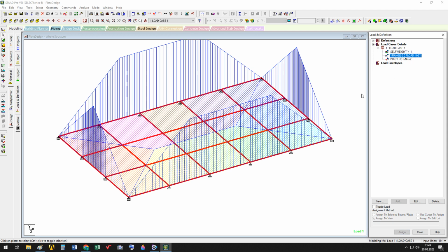Floor load, as you see, is already assigned because of its definition at floor level. Floor load, for example for this beam, is calculated from the floor area as a triangular uniform member load and acted on the beam. As you see, the distribution or the shading goes to the beams, calculated on the floor plane and then distributed and acted on the beams.